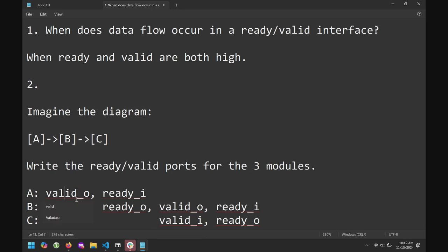And so every time we have a ready valid interface, which takes, I guess, these 4 wires all connected. Technically, it's only 2 wires. But if we have these 2 wires, there's also going to be data that is paired with that. And these wires denote whether the data transmission actually occurs. Cool, there we go, okay. Good. So this is the solution. This is the most common on-chip communication interface.